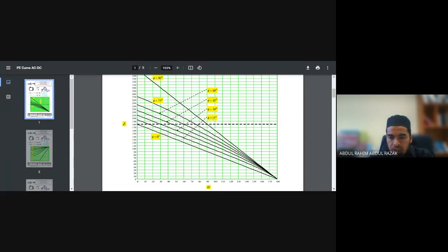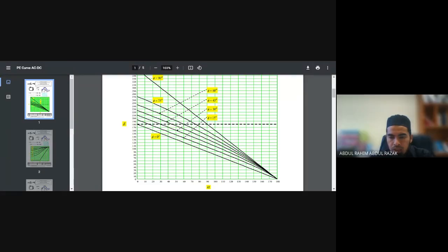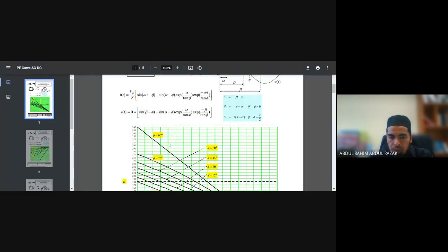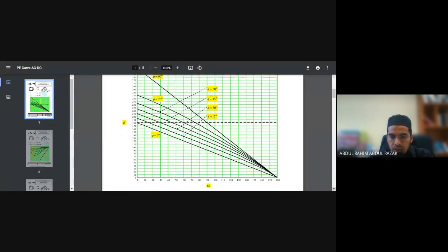If you trigger at 90 degrees, your extension angle will be 90. You trigger further up to 180 degrees, your extension angle will be reduced as well. This happens when only a resistive load is available inside your load. But when you have a more inductive element inside your load, the above curve applies.